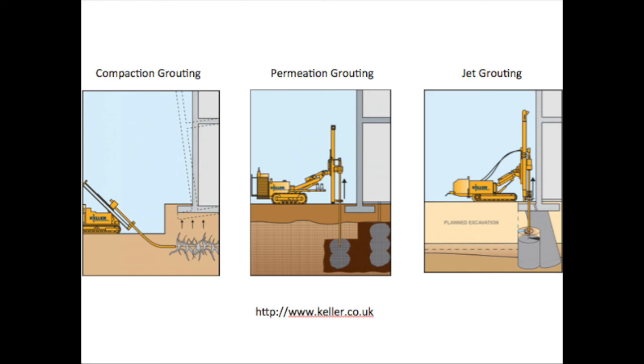Jet grouting is an erosion-based system that relies on the kinetic energy of high-velocity jets to break down the soil structure and remove a portion of it while mixing it with cementation grout. The main use of jet grouting is to create a soil cement column that acts as a wall of an excavation. However, if used properly, jet grouting can contain soil, so that if liquefaction were to occur, lateral displacement would be minimal, which would minimize the amount of force on a pile.